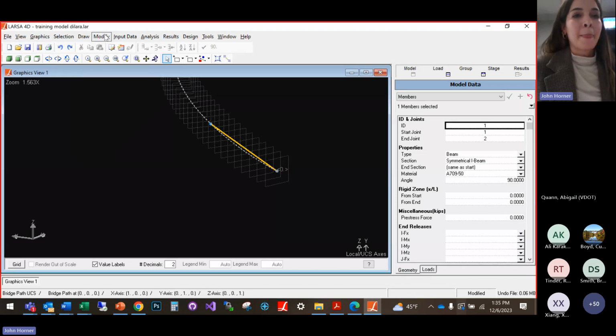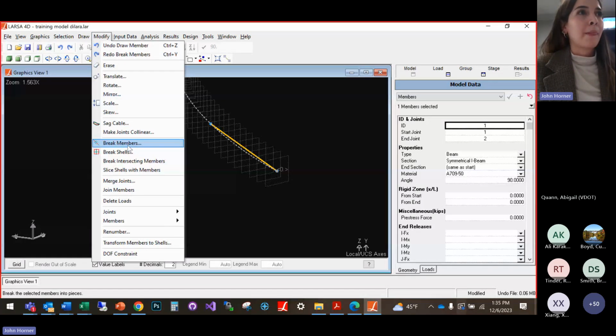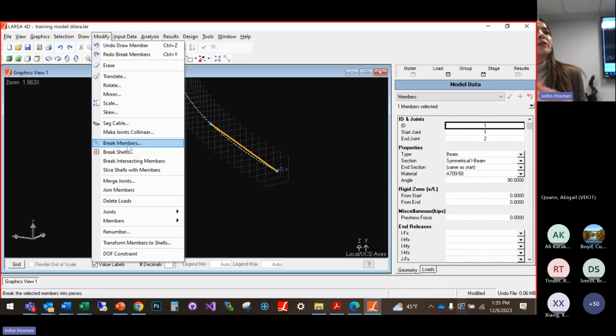Is that delta the half spacing that we're setting there? Yeah, delta will be the deck spacing. It's half of the tributary area. Your total tributary area is going to be 12 feet for girder, and between girders, the spacing is going to be 12 again. So you'll have one to the right of the girder, one to the left, in the model.